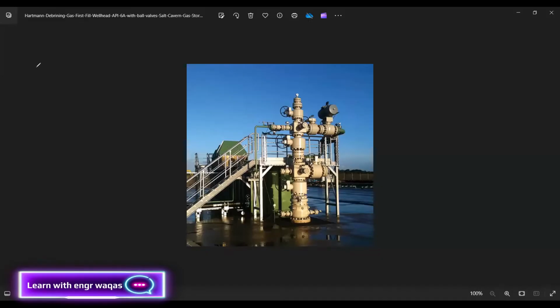You can see over here, this is a valve. As a human being, if I'm sick, the doctor is going to ask for some examination, blood tests and all that. The same happens with oil and gas wells and reservoirs. If something is not going well, we need to run in hole from here. This is the swab valve. This is the production line valve. This is the kill line valve. This is the master valve, and this is the lower master valve. They serve different purposes.